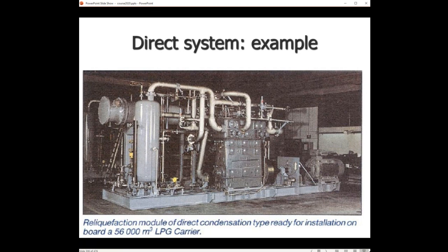This plate here is an indication for the bulkhead that separates the motor room from the compressor room. Remember that in a motor room there is always a positive pressure, while in the compressor room there is always a negative pressure. So it is impossible that motor and compressor are in the same room, as we learned before.